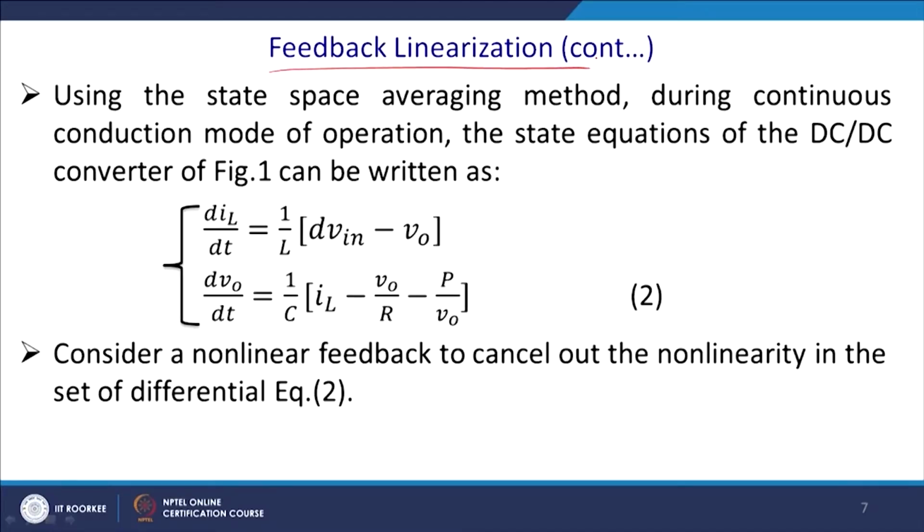Using the state space averaging method during the continuous conduction mode of operation, and please mind it, in all our discussion we have restricted ourselves to the continuous conduction mode, and all those equations are valid for the continuous conduction mode. Our equations and strategies will change, and the system will have degraded performance in case of the discontinuous conduction mode, which we have not taken into consideration.